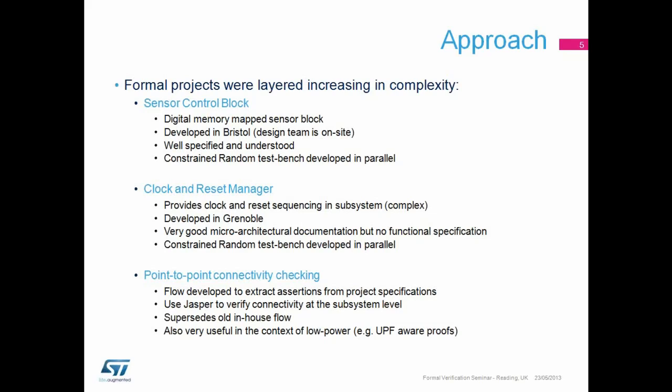Then we did some point-to-point connectivity checking, at the system level. We had an aging SpecMan flow that we'd used for years and years that was buggy, required a lot of maintenance, and didn't really do what we wanted anymore. So we decided to get rid of that and use Jasper as a nice mature industry counterpart. Why have all this maintenance load when we can boot it and use Jasper? So that's what we did.